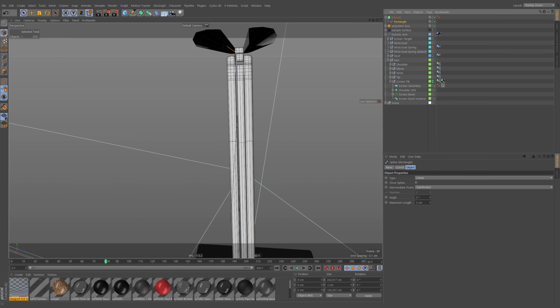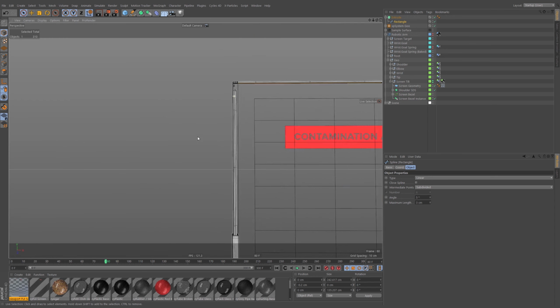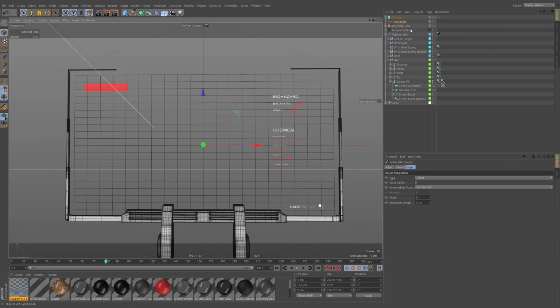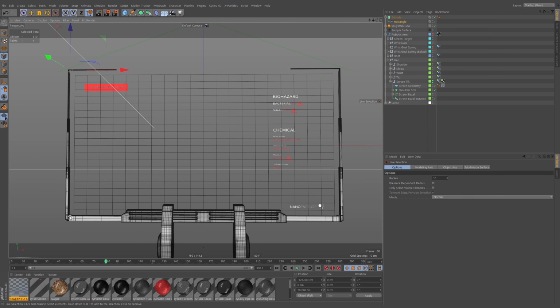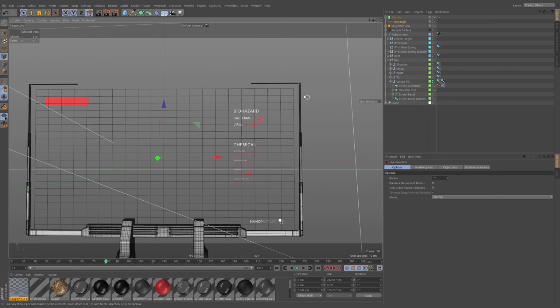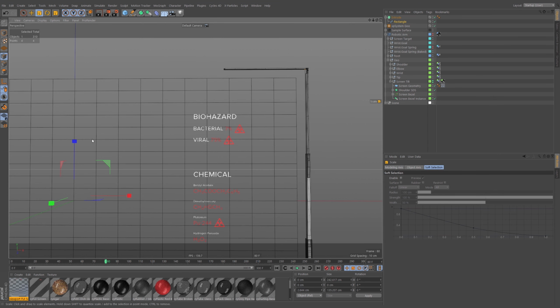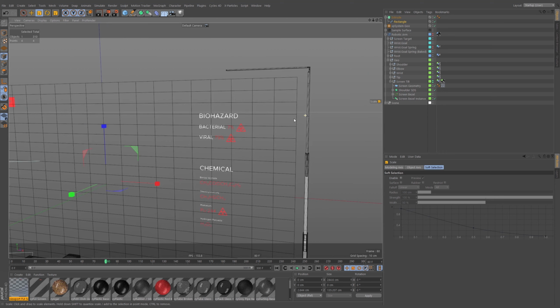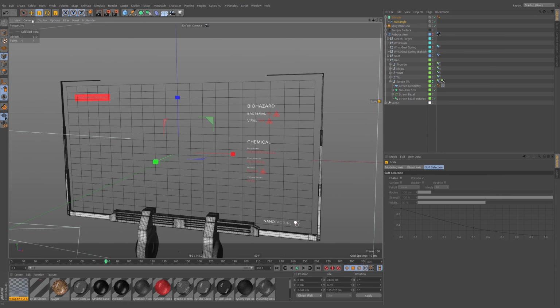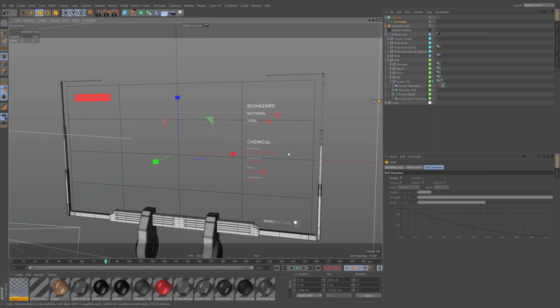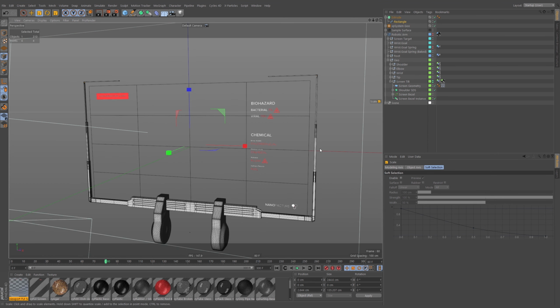I am going to move it slightly off the center axis here. Oh, it was Y, wasn't it? So it was negative Y. Just eyeballing it here. It doesn't have to be absolutely perfect. I sometimes get hung up on detail, so I'm going to ignore the fact that that's not completely perfect. And I am going to widen it a touch so it's just sat inside that zone there. So you can use the scale tool. If I hit T, we can do that. You see there, it just pushes it into that, and I'm pretty happy with that. Okay, so now we've got all that. Let's go back to our isoparm view and clean that up a bit. Just makes it a bit easier to read the scene.